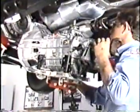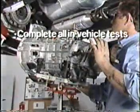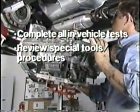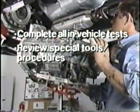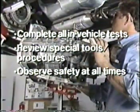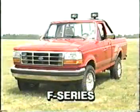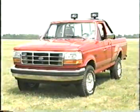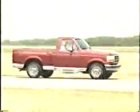Before removing a transmission or transaxle, take note of the following. Be sure you've performed all in-vehicle tests, and be sure you've looked through the shop manual to identify all special tools and special procedures required. When you begin disassembly, you'll find the general procedures are similar for most models. Let's use an M50D rear-wheel drive transmission found in many F-Series trucks as an example to illustrate these common procedures.